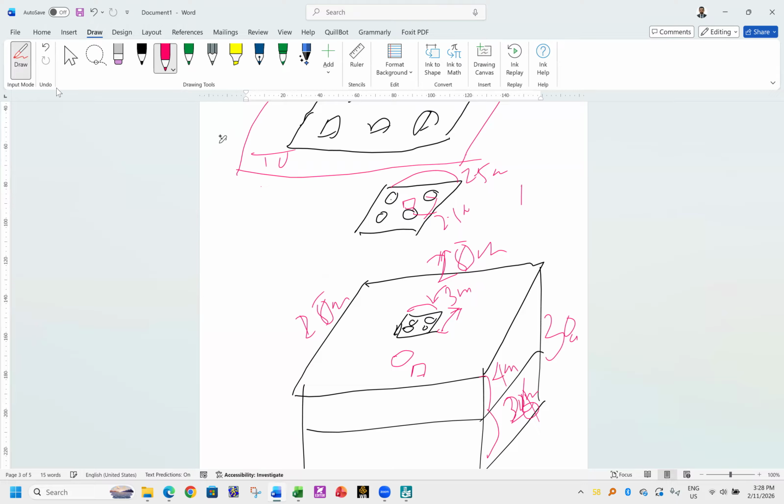Then center to center is 0.6 into 3. How much is that? 1.8. So at the center to center it will be 1.8 meter. So you have to draw it first, then go for the Plaxis analysis.